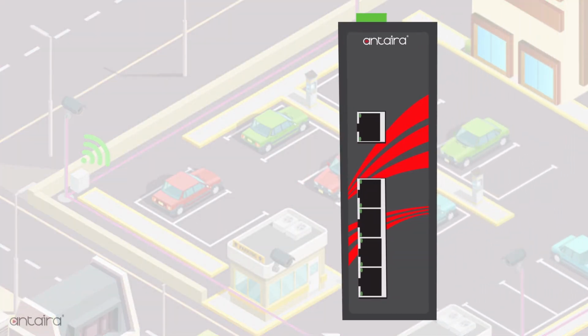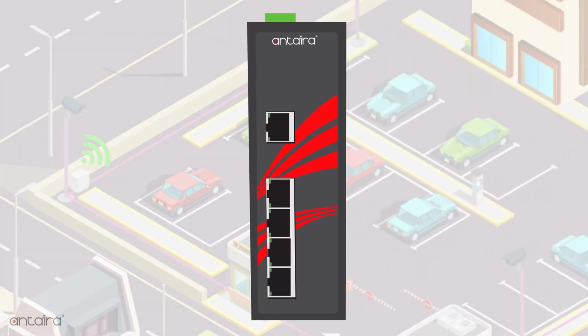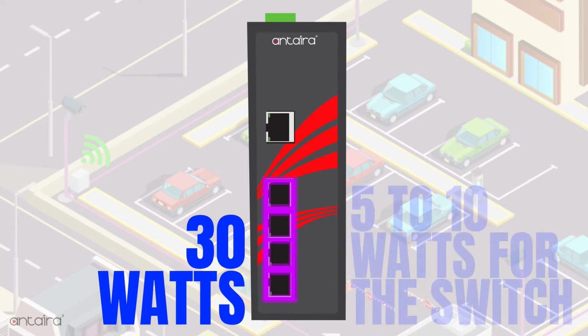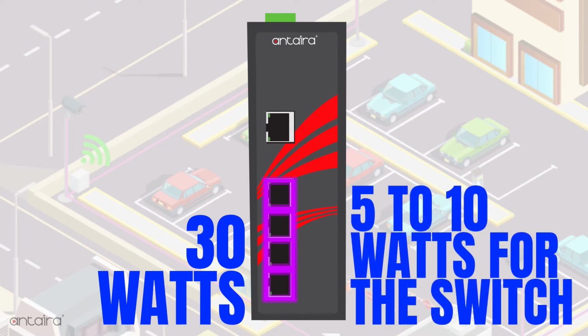Often, a rough estimate can be made by counting the number of PoE ports on a switch, assuming a maximum power budget of 30 watts for each port, and then adding the power consumption of the switch. While this will cover your application, it could cost you quite a bit of extra money in panel space.